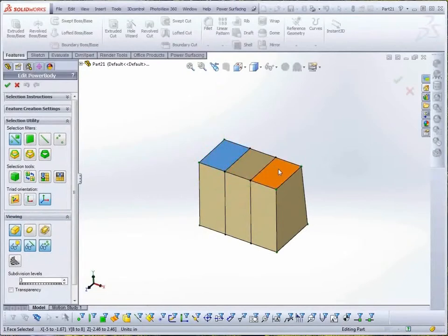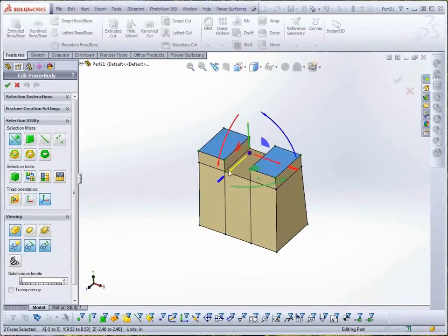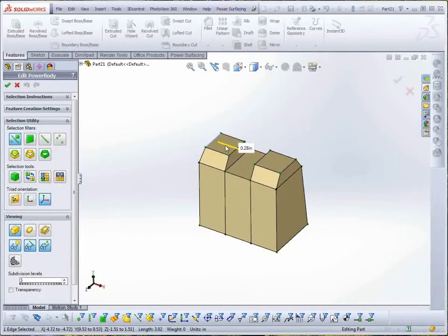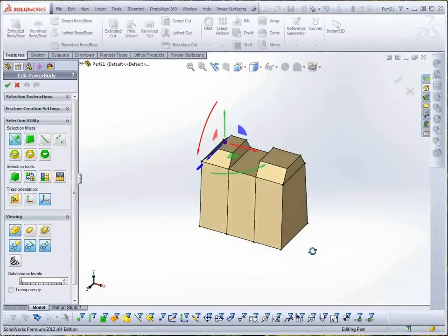Back on top, I'll select the two outer faces by holding the Shift key down, then switch to the A key while pulling the Z-axis of the triad up for a quick extrude. While I'm there, I'll scale them in a bit, and move the front edge back to start to define the slope where the spout will go.